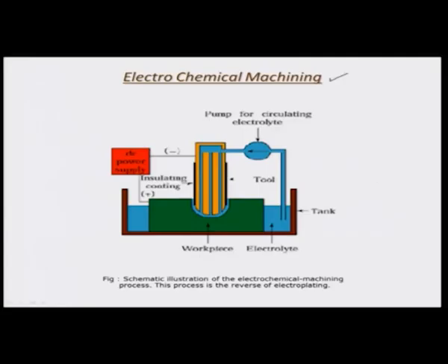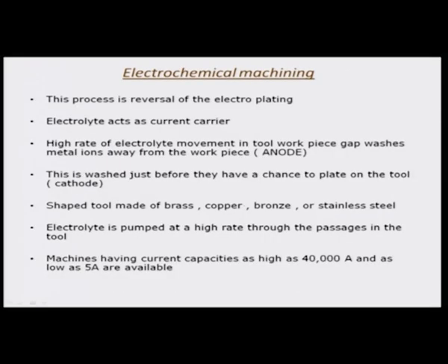So, let us look at some potential applications, and just to illustrate once more, the ECM process is about the electrochemical transport of material from a positively charged workpiece made the anode and a negatively charged tool center in the presence of an electrolyte. Okay. This is a sort of schematic or a cartoon which generates the ECM process, and the process typically is a reverse of electroplating.